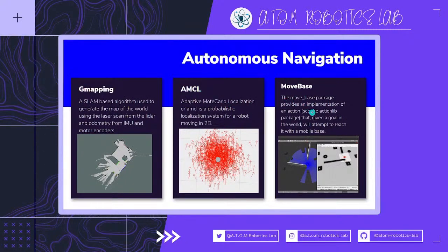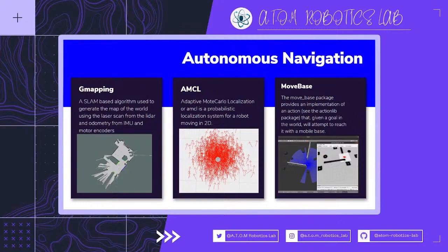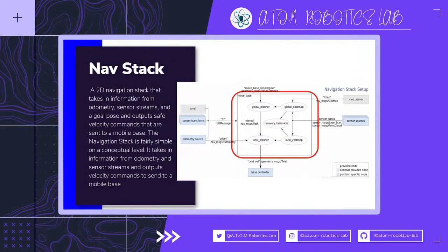And move_base, basically, is the main part of the navigation system. It controls how much twist value we need to give to cmd_vel, taking all the messages and acting according to them. Move_base also handles all the planning algorithms.